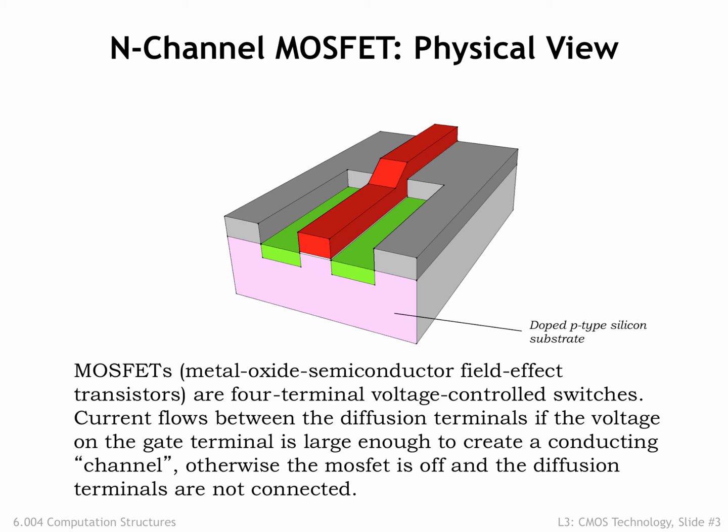The substrate upon which the IC is built is a thin wafer of silicon crystal which has had impurities added to make it conductive. In this case, the impurity was an acceptor atom like boron, and we characterize the doped silicon as a p-type semiconductor. The IC will include an electrical contact to the P-type substrate called the bulk terminal, so we can control its